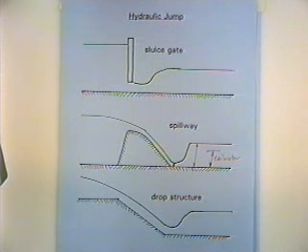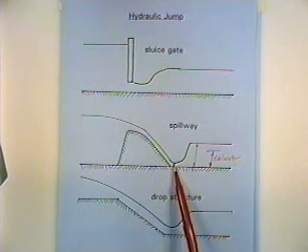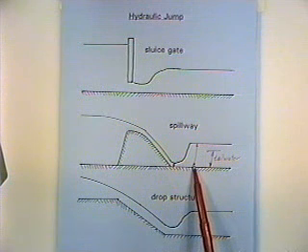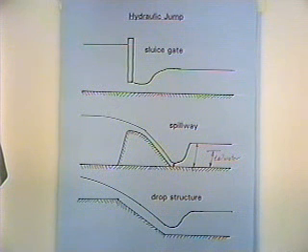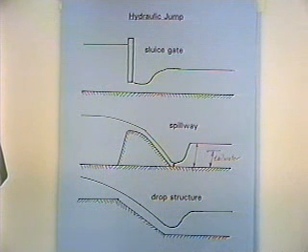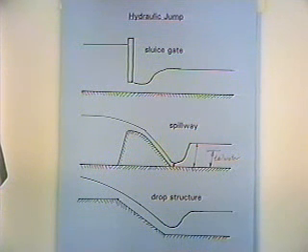Let's go through the computations again. The last example, I used conservation of momentum. Given the depth before the jump, I computed the depth after the jump. I did it correctly. I'm not going to make a mistake here. So that is correct. Now, I did another very conventional type of computation. I started, say, back in a river that the discharge channel is discharging into. With an elevation there, I computed the tailwater depth. I worked my way back upstream, standard step method solution of the energy equation, and I got a depth right here, which is different than that depth. So what's the right depth? What's happening here?